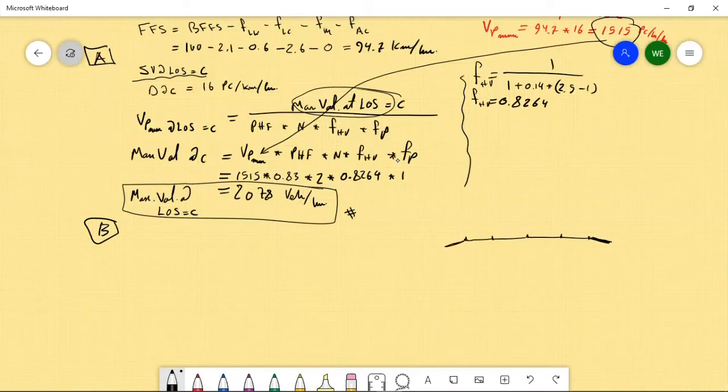So we had a total lateral clearance equal to 3.0 meters. Remember, in case of no median, the total lateral clearance equals 1.8 plus the right hand lateral clearance. That means the right hand lateral clearance, or the shoulder in this case, is just 1.2 meters.